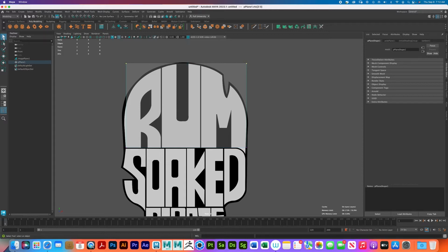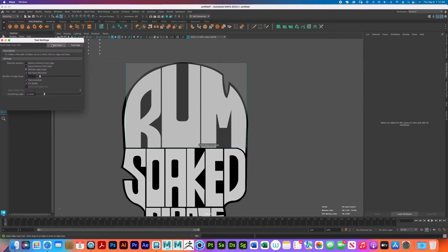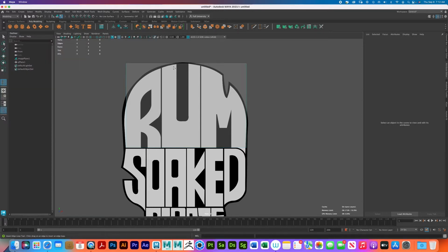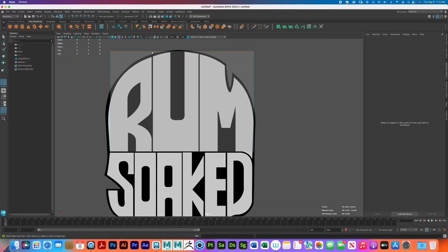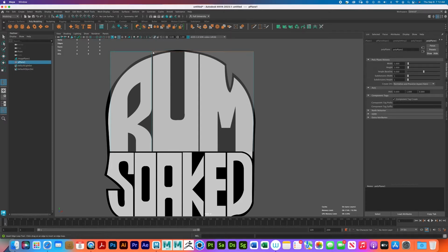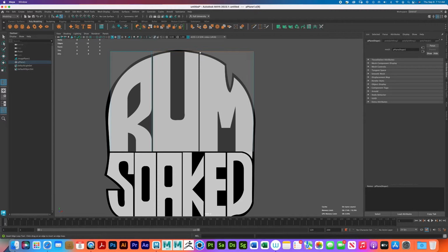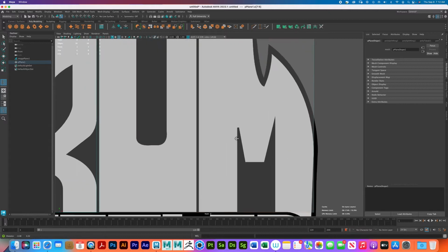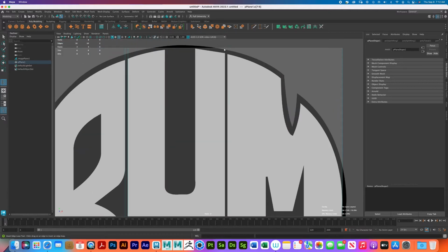So first things, mesh tools, insert edge loop. Click on the little box here and reset it. Close it. Now you're going to click and drag that, you see my dotted line, to where I want it. Click and drag. I'm going to do it again, guys. Sorry, click and drag to about there. And again. Let me zoom in, guys, because I'm not seeing too well. I'm going to go here and do this one more time right there.